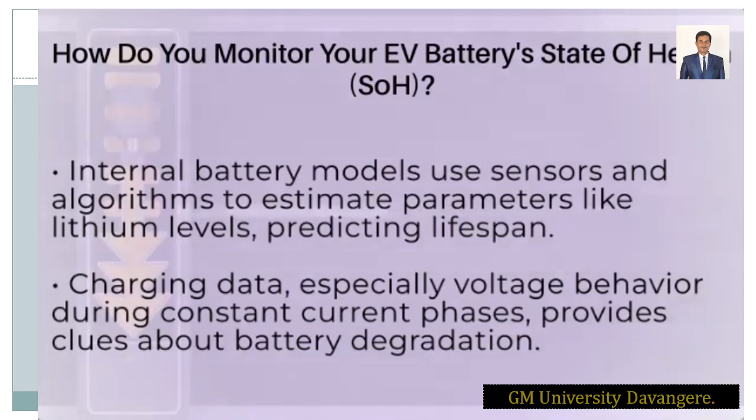All right, so let us see what components are required to use the sensor. For using the sensor, you need to collect the voltage, current, and temperature from the sensor of each cell, right? And also try to have the internal model in the BMS. Every input data has to be collected every 100 milliseconds, right? And then think about one block of each in the BMS architecture.